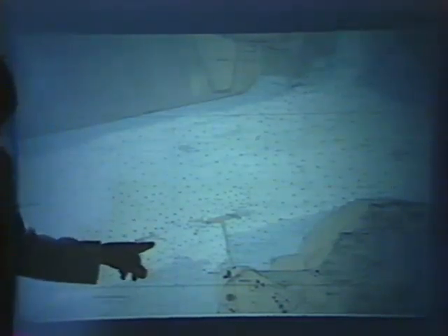In view of the high cost of dredging, you can see that making a terminal that doesn't require dredging is much more important than providing a causeway for a pickup truck to drive out. Well, the points I want to bring up are, if you're engaged in something like this, by all means go out and make current measurements at the location, in the area itself. Don't depend on any model. Actually go out and make those current measurements so that you know for sure that the orientation that you have is right.